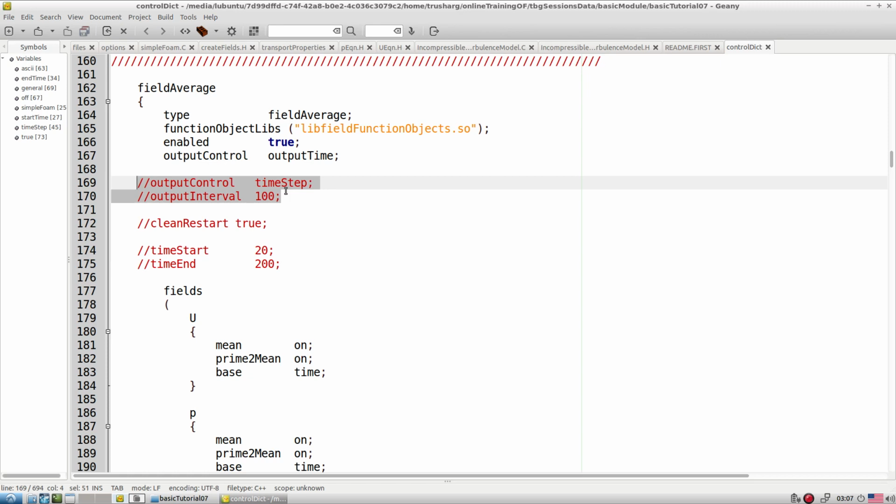What is phase averaging? Let's say we are talking about flow over a circular cylinder. Our flow becomes fully developed when we see the lift or drag plot over time, where consecutive peaks are reaching the same level. Then we say our flow has become fully developed. But we are not interested in the entire averaging; we are interested in what happens at the flow peaks. So we have to accumulate, let's say, 100 peaks or 20 peaks, and do the averaging only for those particular peaks.